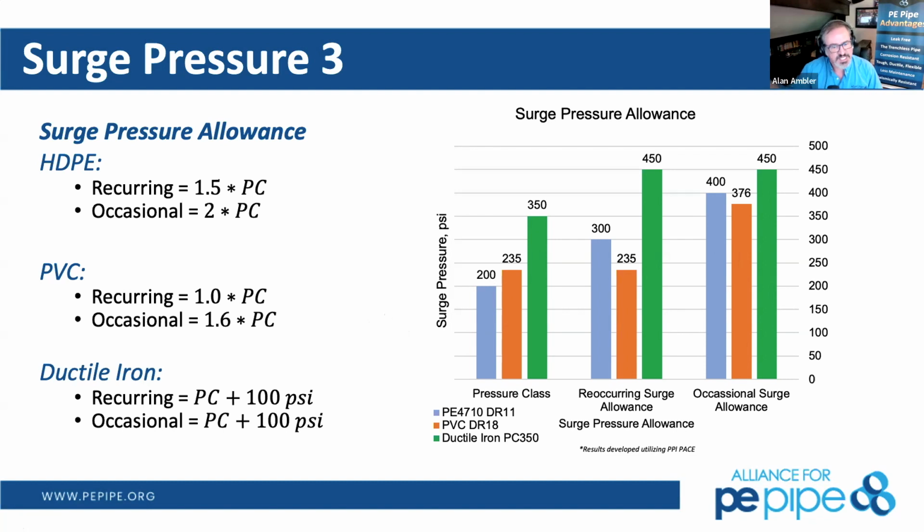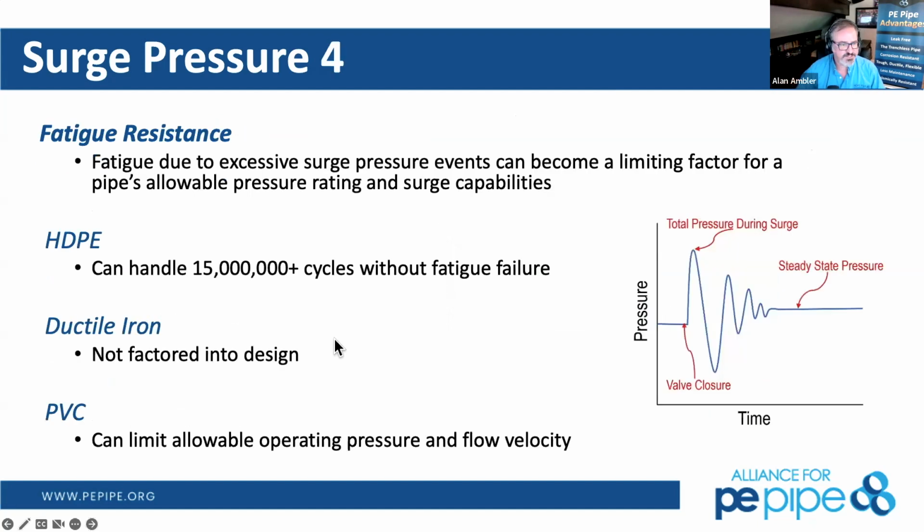So they often try to keep the velocities a little bit lower, in that 2.5 feet per second range, from what we're looking at within the flow of the pipe. So go ahead and advance. So again, I mentioned cyclic fatigue. Over the lifetime of that pipe, when we have those surge changes, as we're predicting the lifespan of the pipe, that's where that cyclic fatigue comes in.